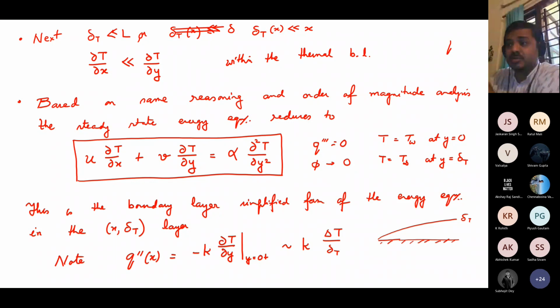You may ask me, well, you just said that the two boundary layers are different. Yes, true, but as we will see later as well, the growth is similar. Okay, there is a pattern. The momentum boundary layer also grows in the x direction. The thermal boundary layer also grows. Now, which one is thicker, which one is thinner? That is decided by the Prandtl number, nu over alpha.